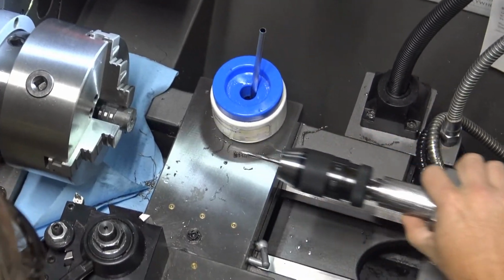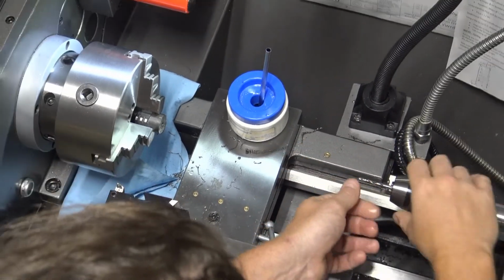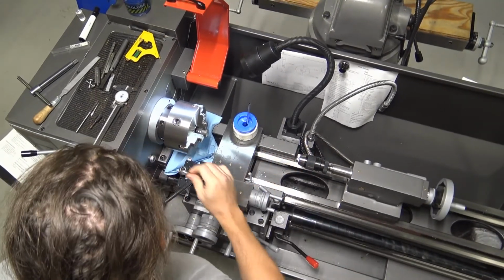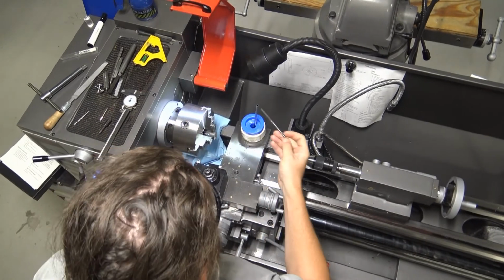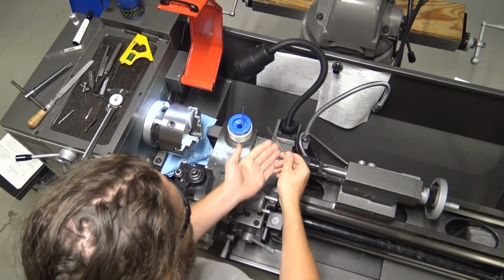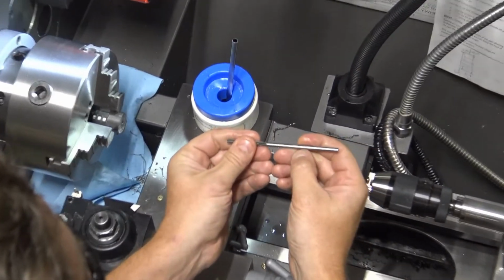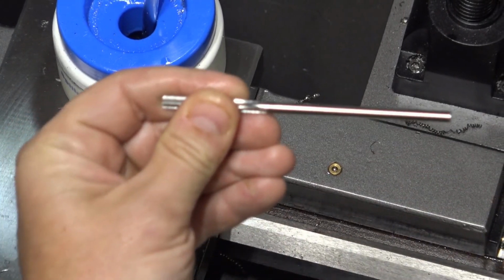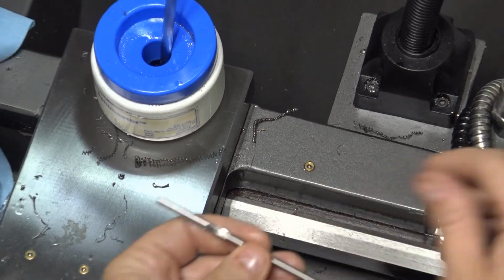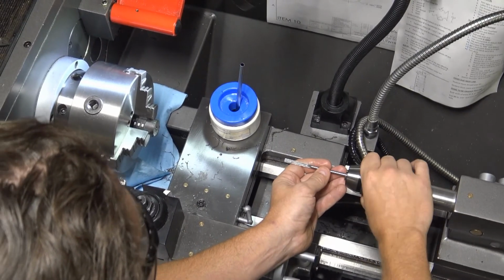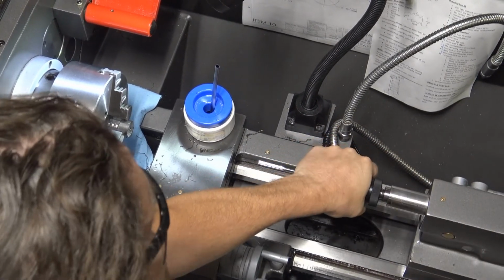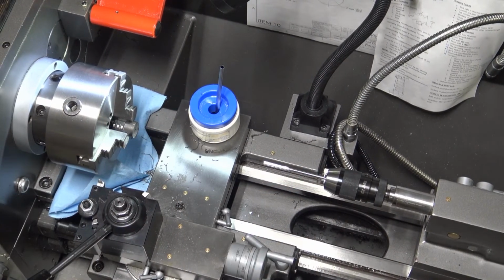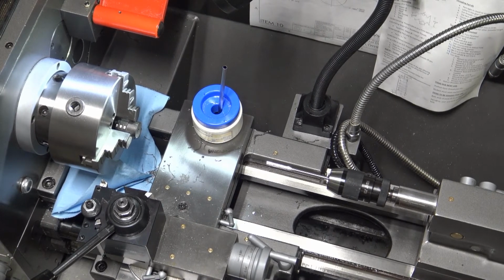Alright, so I drilled that out. And then the next thing we're going to do, step 4, will be to ream with the .1885 reamer, right? Based on our tolerance, we wanted to choose this reamer. And it should say it right here. You guys won't be able to see it on camera, but for me, I can see that it says 1885. That's the reamer we want. So it's going to be a little bit larger than the pin that's going to go through there on final assembly. And now we'll have to slow our speed back down for a reaming operation.